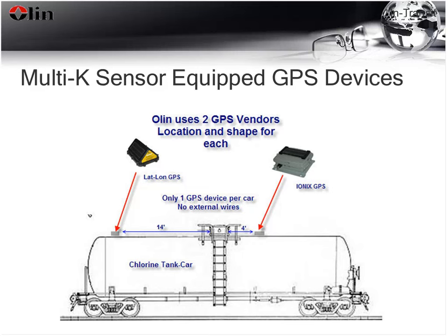So as part of our goal to create the most comprehensive records we can on every shipment, we have our fleet equipped with several thousand GPS units from a couple of different vendors. And we mount them on rail cars as shown in this diagram. And I think the location of your GPS unit is important. As David mentioned, sometimes a force is concentrated, especially in an undamped system, and those forces may not propagate fully down to your GPS location.